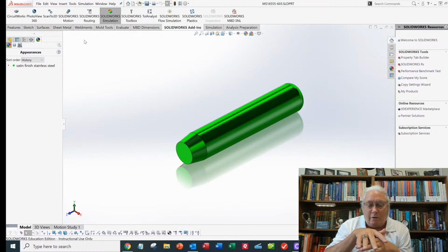You can define those thicknesses and those anisotropic materials in each layer, and each layer has its own direction where it's going to be stronger, obviously along the glass fiber direction, or whatever your reinforcement material is, whether it's nanotubes or fiberglass or glass fibers.